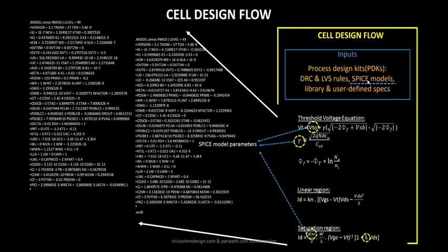You have to use these spice model files, the DRC and the LVS file as an input from the foundry, and design your inverter in such a fashion that the inverter you have designed follows these particular rules given by the foundry. Okay, and finally you have the library and the user defined specs.